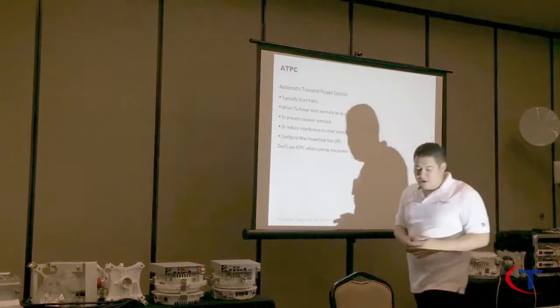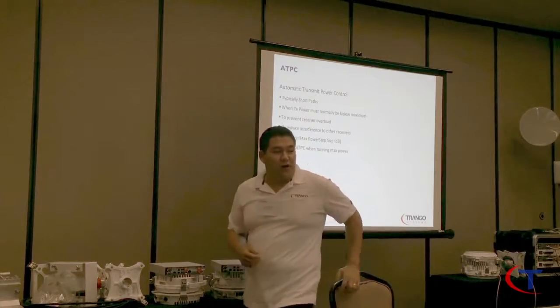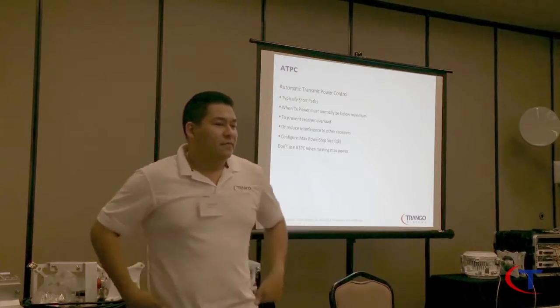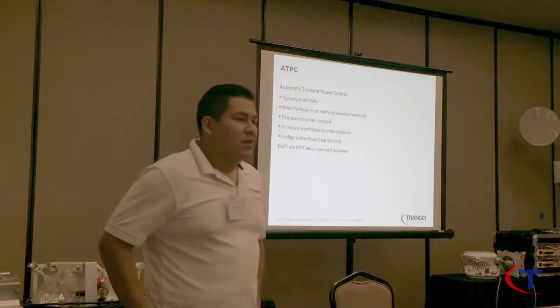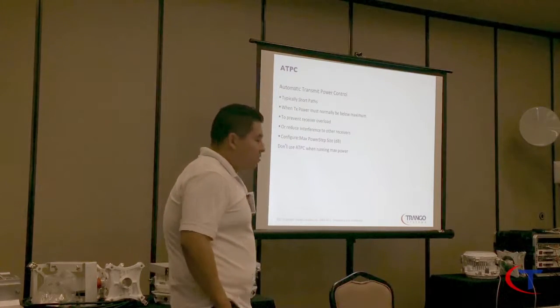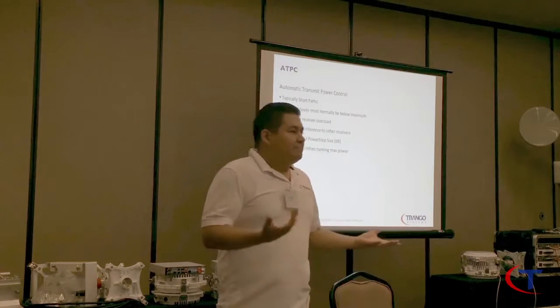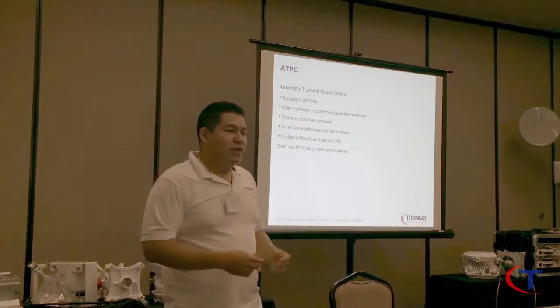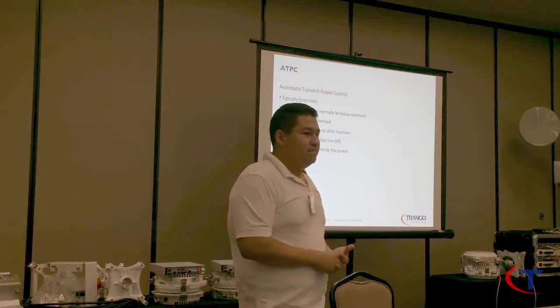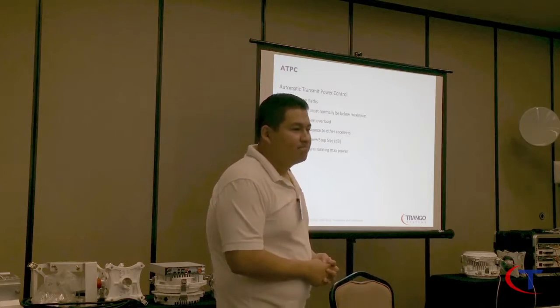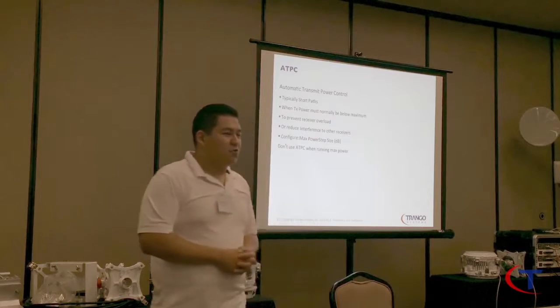So back to your question, no, it doesn't harm the radio if you have it just powered on. Even if we're not using ATPC, it's still okay. You're not going to hurt the radio. You can turn it on and leave it on the lowest power. It will be leaking RF, yes, but it won't damage anything. Even if it was on highest power, it's not going to hurt it. You will just say your MSE was really bad. That's all.